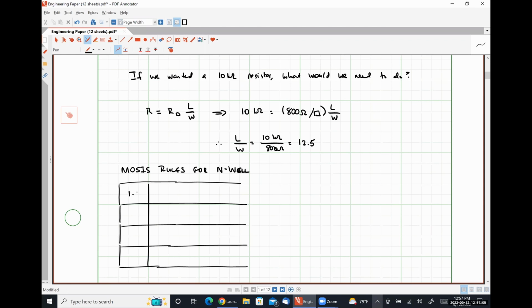So there are lots of different foundries that support lots of different CMOS technology nodes. At this point, the lowest common thing would be the onsemi C5. That is a 300 nanometer process node. So 300 nanometers is your scaling factor lambda, and since through MOSIS rules it usually has a minimum of 2 lambda, you're actually looking at 600 nanometers, or half a micron, as the smallest transistor channel length that you can achieve.